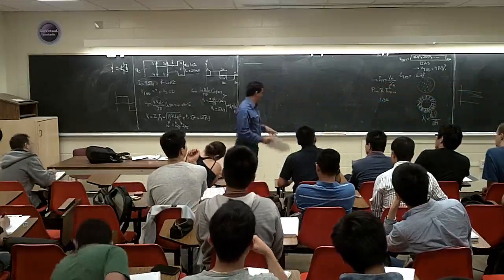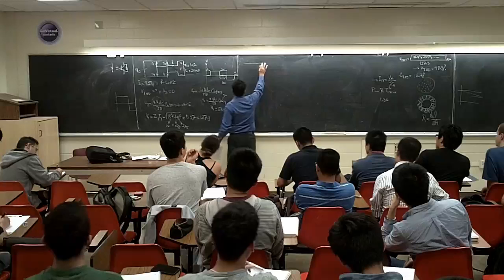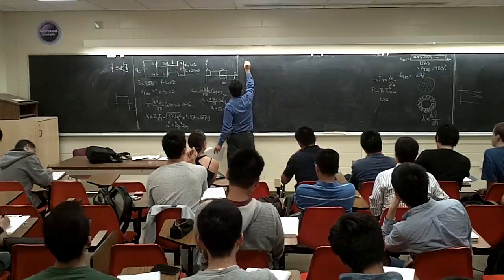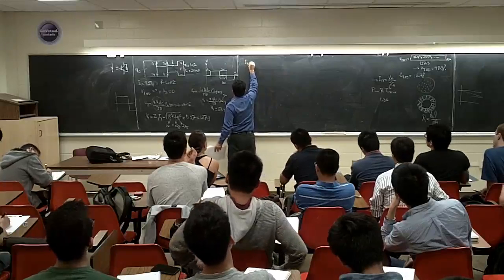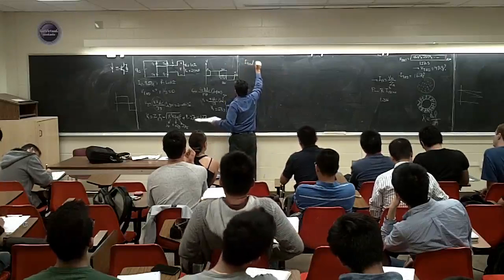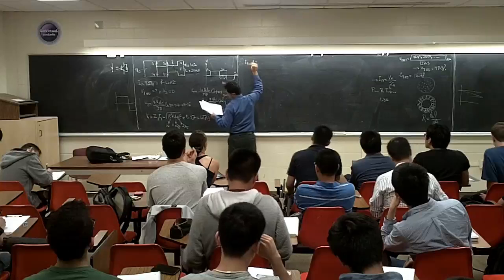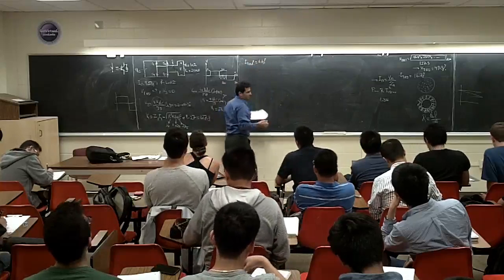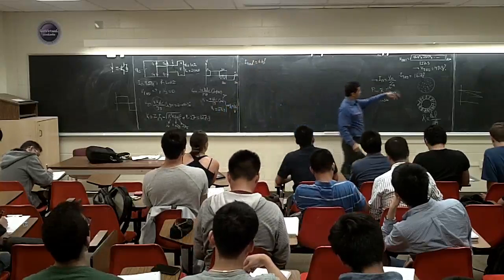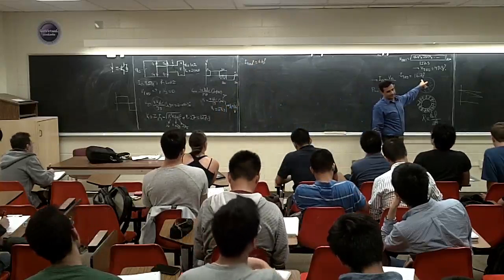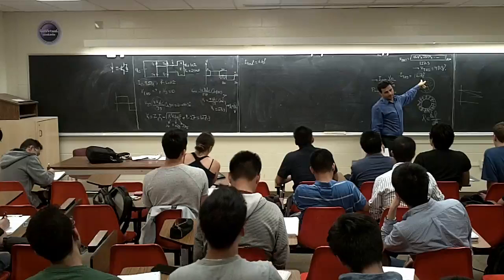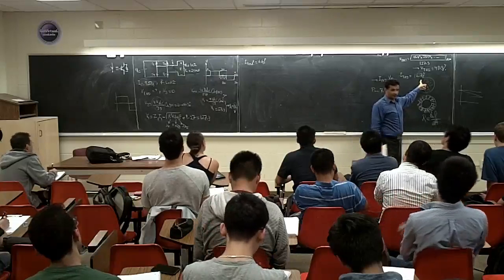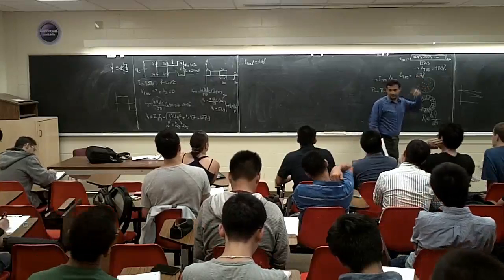If you calculate those things, what you're going to get for your current THD, if you calculate those ones, you're going to get 6.6%. Did I get it? How much improved? 10%. Just getting rid of the third harmonics, we got 10% there.